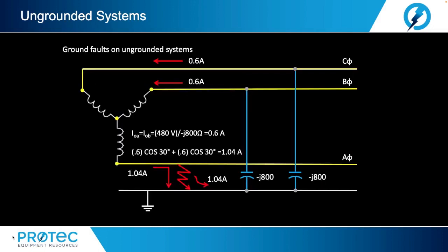Now, many people are of the opinion that an ungrounded system is safer. This opinion says that since contact with a single phase does not complete a circuit, one should not get shocked. This is not the case because capacitive coupling to ground is present. In the example shown, a sustained ground fault occurs on a 480 volt Y connection. It could be a delta ungrounded system.